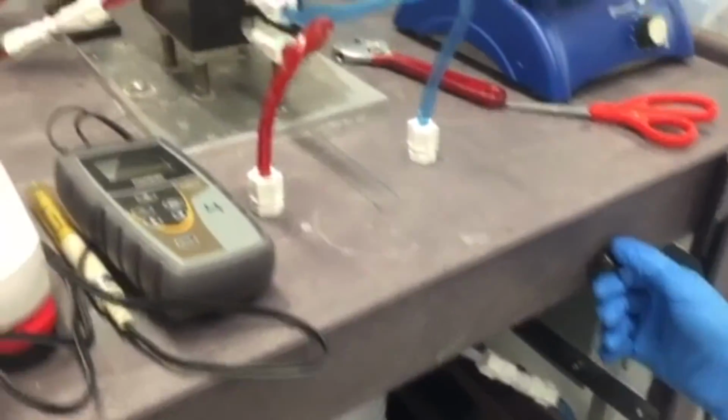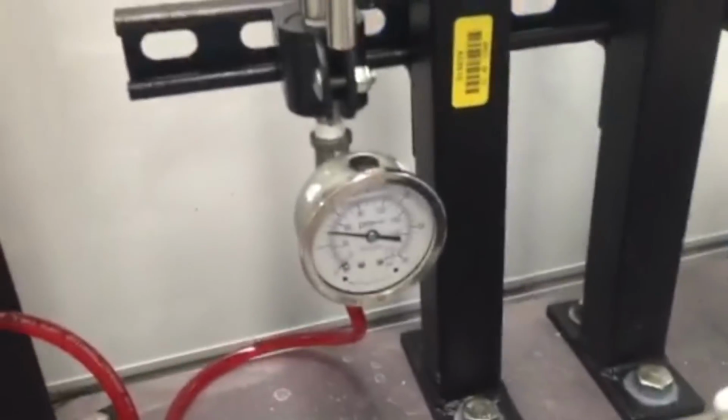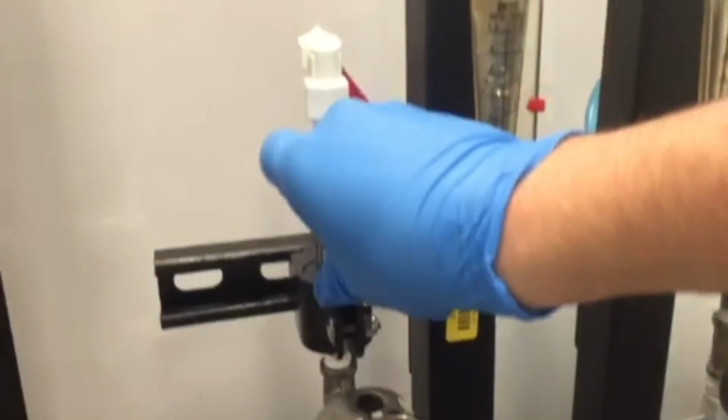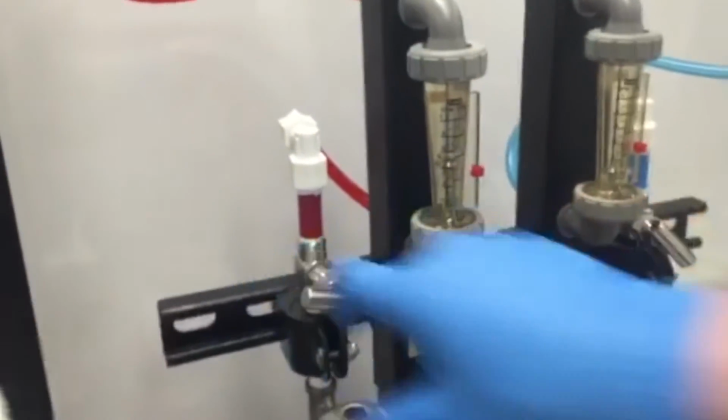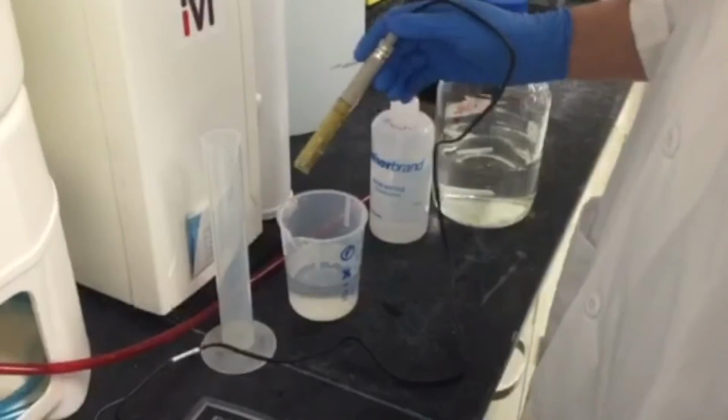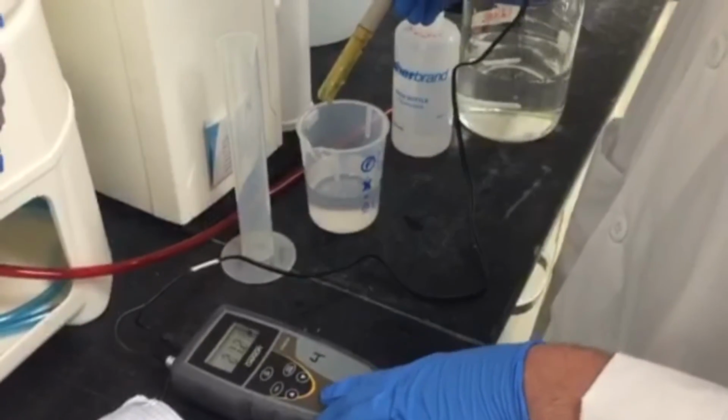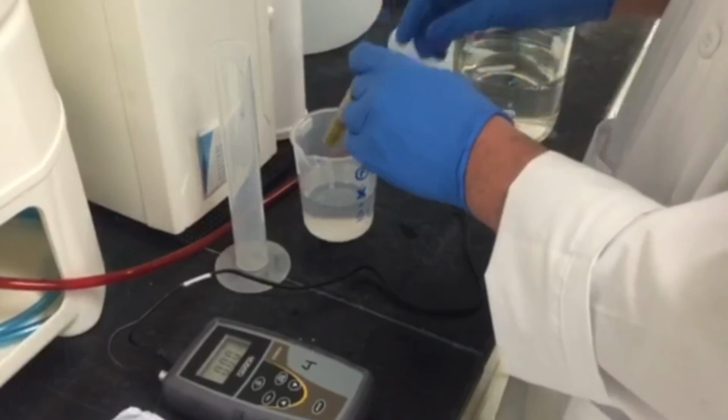For this experiment, flow rate remained a constant 1 milliliter per minute and pressure was adjusted from 4 psi to 6 psi and then to 8 psi. Calibrate the conductivity probes using solutions of different concentrations. Make sure both the metal bands on the probe are covered.